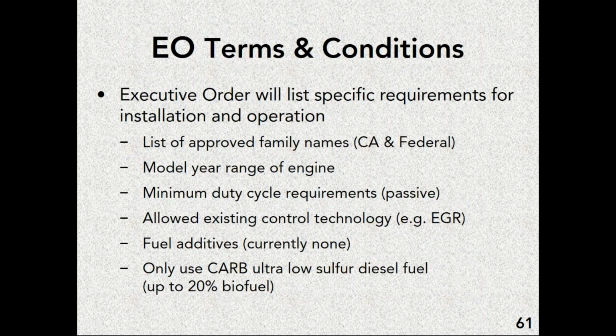The executive order on the filtration is going to list the specific requirements necessary to install and operate any of these filters. It'll give you a listing of the family names, the model year range of engines, as I said earlier, the minimum duty cycle requirements, whether it's passive or active. If there's technology on the engine that will cause problems, sometimes an EGR system will actually negate the ability to use several different filters.